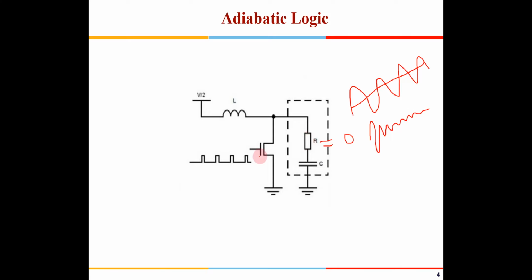Okay, just to prevent that, you have an NMOS here, where you can give a regular pulse out here. So whenever you give the pulse here, a high current from the source will flow like this, right? So energy comes into the circuit. So once it gets switched off, obviously this current cannot die instantaneously, right? Because it is an inductor. So that energy gets stored into the capacitor. So this way, by giving small pulses through an NMOS out here, a small amount of energy is being taken from VDD.